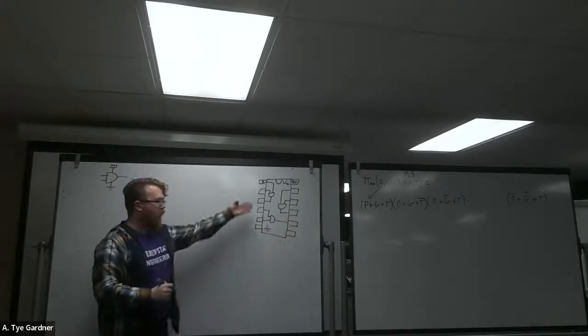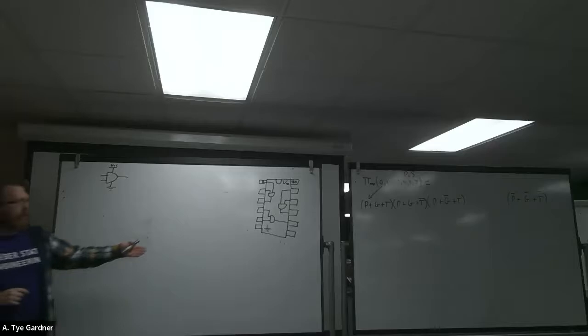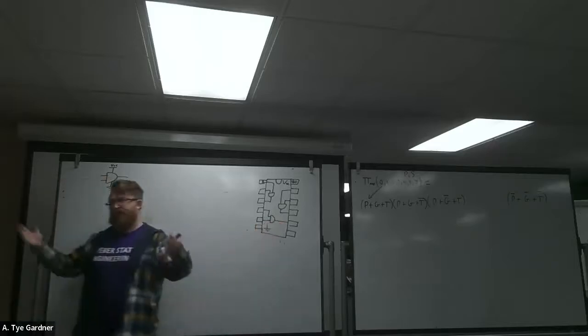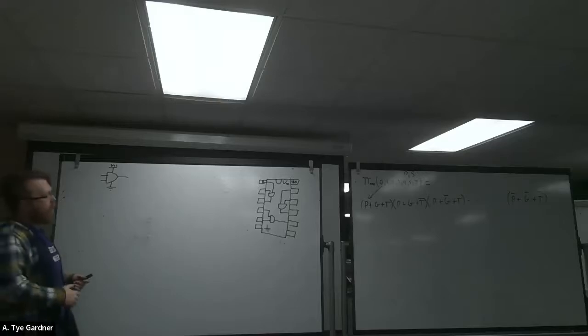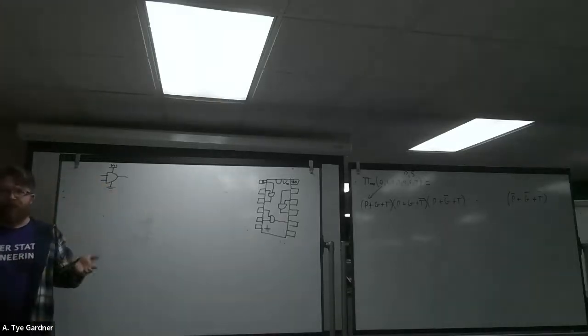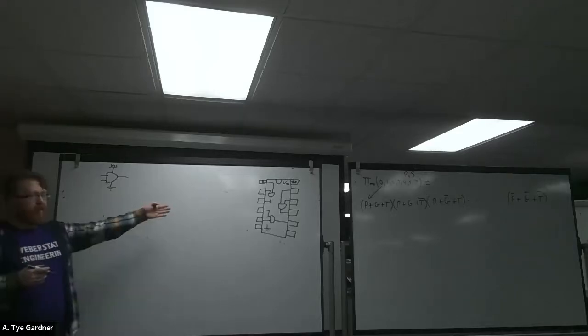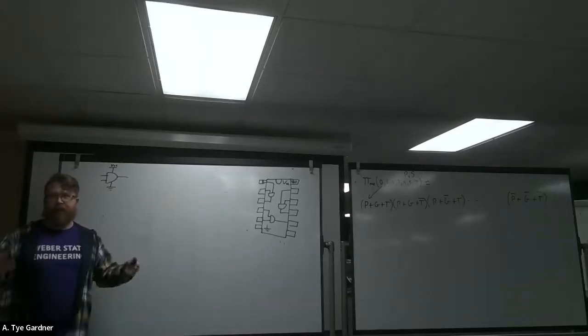Okay, there we go. You will see weird packages like this sometimes. This one's weird, right? Because there's one extra floating pin. It's fine, it's not a problem. Now, what's interesting about the 2 input AND gates is I need to draw 2 more lines. But let's say I've given you this package and I want you to build me a 4 input AND gate.